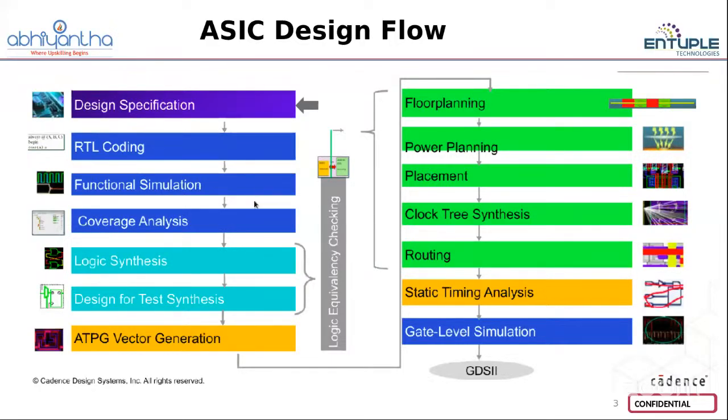This checks whether whatever logic was inferred in the RTL code has been completely developed in the synthesis stage or not, which is called logic equivalency checking. We can do this logic equivalency checking at any stage after the synthesis process. Once the synthesis process is ready and the synthesis report is there, after the floor plan, we go to the physical design side.